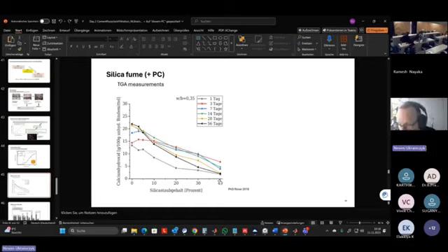If you want, you could almost calculate the exact degree of reaction that we need to get not zero, but 2.5% of portlandite. You just need to combine this example with yesterday's calculation of phase assemblage, and then you can. Yeah, I think it's also a very easy engineering exercise to calculate this.